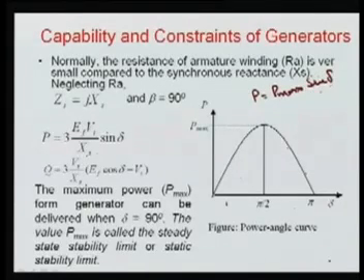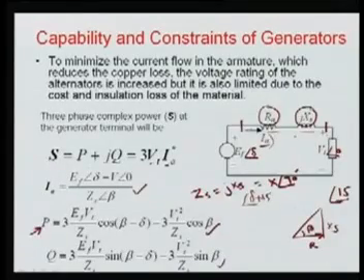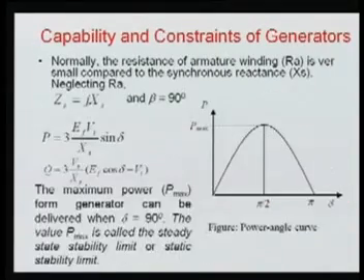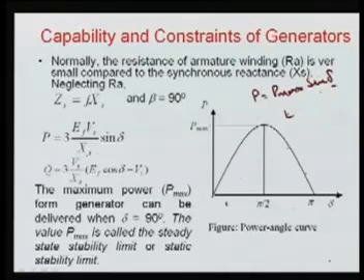This delta is basically the difference of the voltage angles of the two buses. Here, for example, I represented this system. This is your EF and this is your VT. So it is a voltage angle difference between these two points. Here, EF is at angle delta and your terminal voltage was at 0, so this is the difference between these two angles.